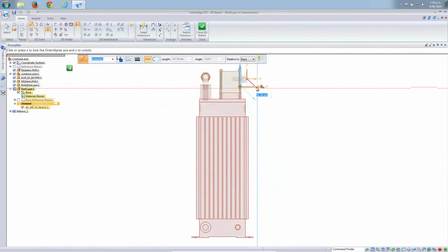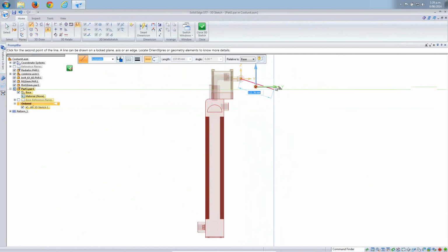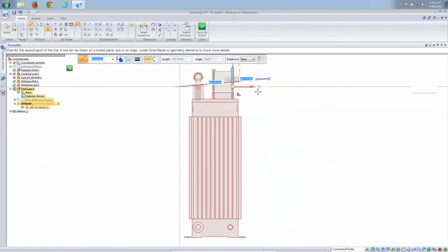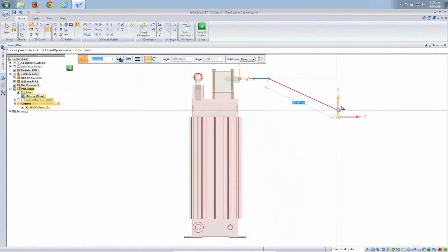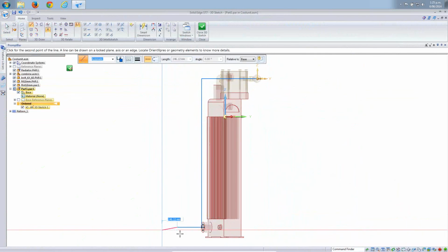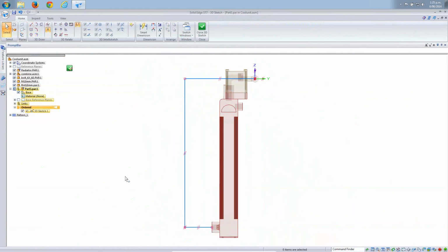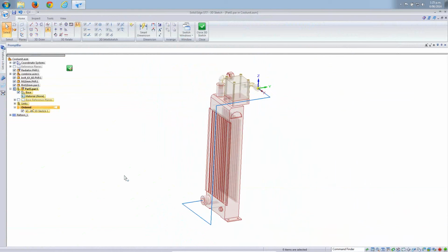In a front view, I just want to run along the x-axis. In a right view, we just need to run along the y-axis, so we'll pick that. Again, front view again, I just want this to run down. Let's move the axis down the z-axis, but it needs to line up with this port. And then we'll set the x-axis as well. And then finally the last part of this pipe run runs into that port at the bottom.